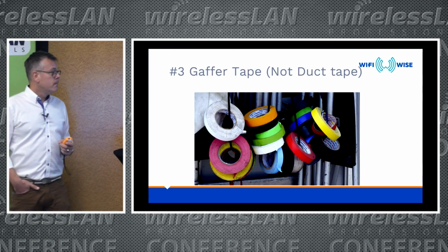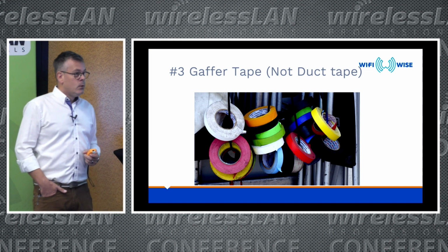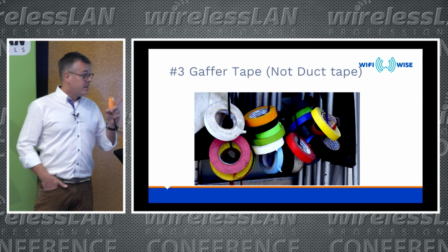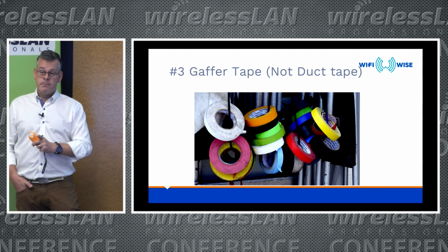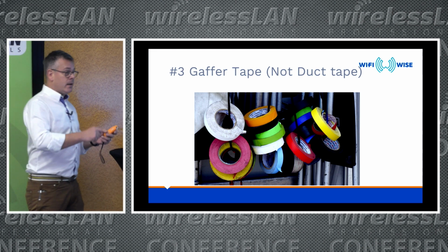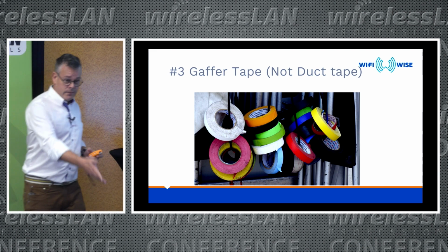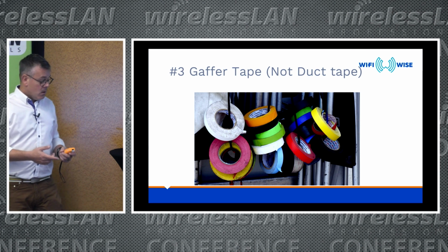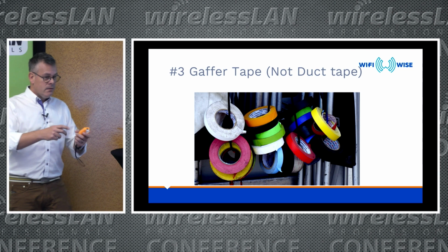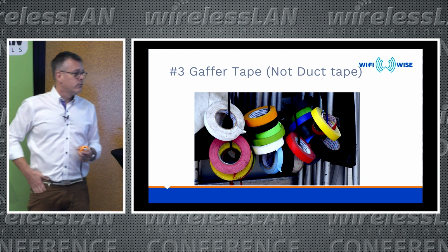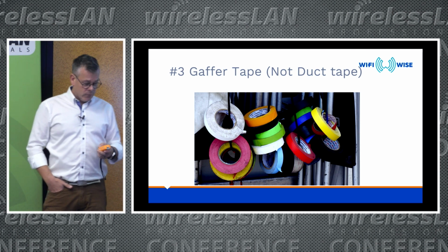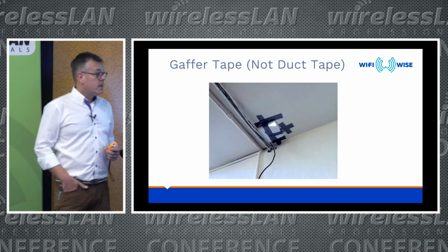And one of them is Gaffer Tape. We used lots and lots and lots of Gaffer Tape. And mind you, Gaffer Tape, not duct tape. Because gaffer tape, you can tape it somewhere and then take it off again, and it's really sturdy. You can stick it anywhere. Look at the cables here. And the good thing is you can also remove it. It doesn't leave any plastic residue or anything else. So you can hold down cables, and you can stick APs to a ceiling.